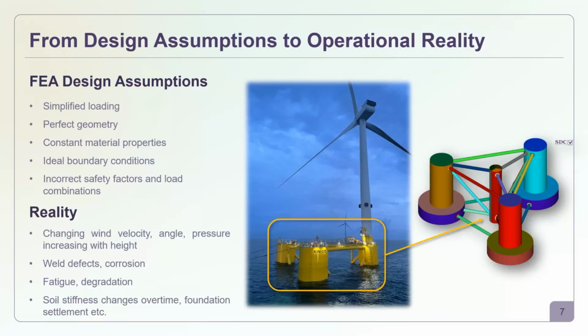If you simplify it too much, if you don't include some crucial details, some crucial connections, maybe some welds and so on, you might end up with results that are passing your standard checks, but reality might be different since it is not included there. So, as I mentioned, we will cover it later, but it is important to represent your structure how it is in real life.